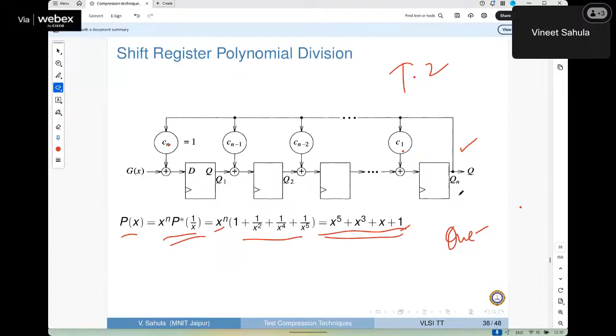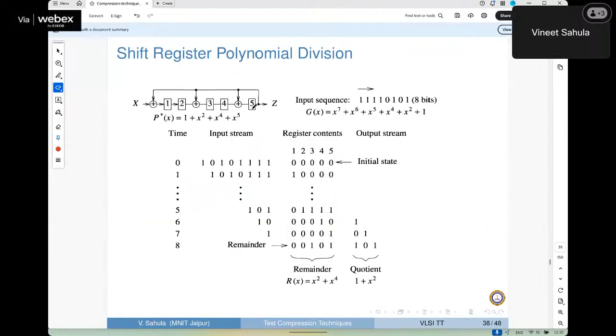So my x^n will be here and my 1 and x will be here. So 1 is necessary. I will take x. So this is there. This is not there. X5 has to be there. So this is already there. 1 is there. And this x4 is not there. I will choose those taps and realize my LFSR. This is my LFSR. Right? Realize with P star. It is one to many, so it is type 2.